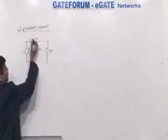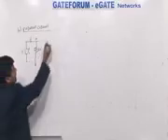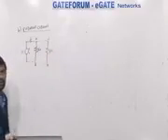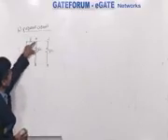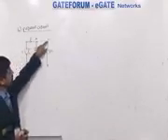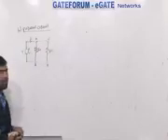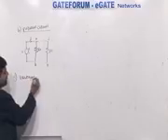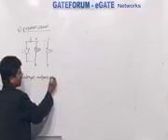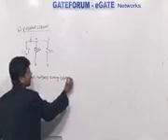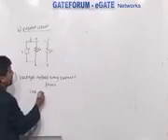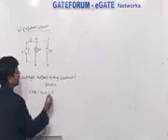Due to that, current of I ampere will flow. Now, if you observe this circuit carefully, in between C point and D point, resistor R2 is there. In between A point to B point, resistor R1 is there. Now, one can say from this that these 2 points are same like these 2 points. So, voltage across every element remains same. So, what is first property of parallel circuit? Voltage across every element is same. So, I can say VAB is equal to VCD, which is equal to V.